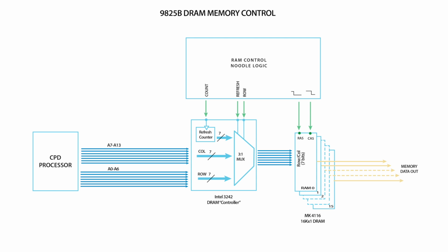And it does that using some inputs from the processor. So what are those? There are not that many. The first one is ADDR. It comes out of the memory decoder, and the upper 32K bytes indicated by A14 would be the RAM, but they added some slivers of ROMs, the plug-in ROMs that go in the front of the machine, so they also need to look at A13 and A12 and subtract that from the addressable RAM space. Nevertheless, A14 is important. They pass it directly, and basically when A14 is at 0, you know for sure that you are in ROM.